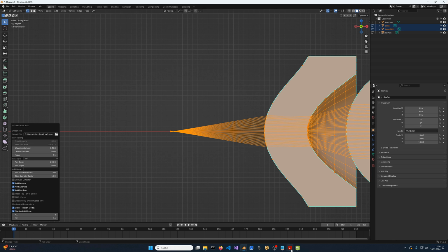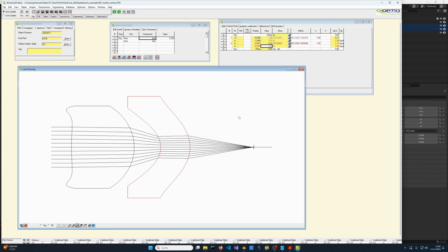Now, to do a further cross-check, I have also built this lens in the free version of WinLens, a software that I've shown previously in my older videos, because it's an optical design software of which there's a free version, and I've set up the lens according to the patent specification in here. Now, the first lens looks a little bit different because it actually doesn't cut off the surface just beyond the initial stop size as it should, but it keeps rendering it out to higher distances. So it looks a little bit different, but other than that, it's the same. And if we look at the surface table here, there is the back focal length indicated in this field. And this is calculated automatically, so I cannot edit this value, as you can see when I double click. And it's rounded here, 1.83, only shows 2 decimals, unfortunately, but it gives the same value.